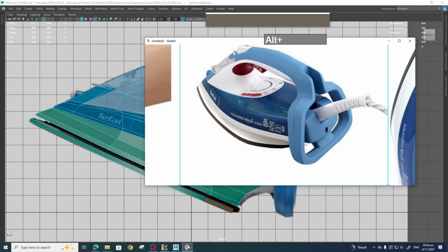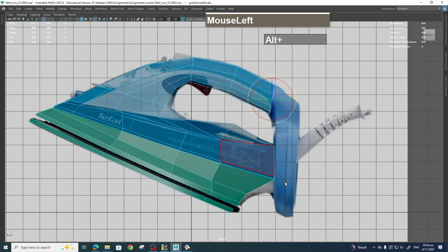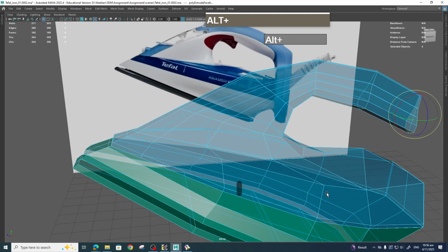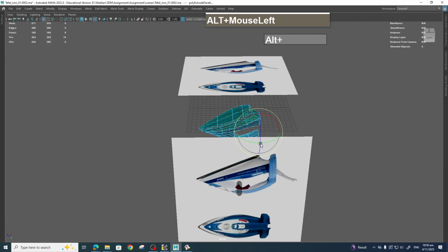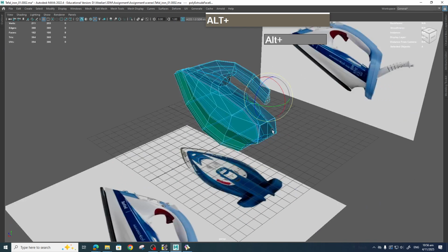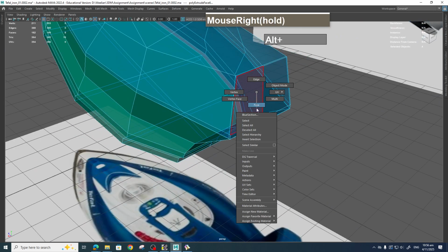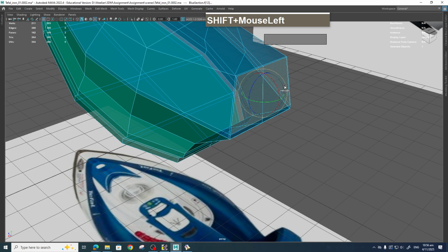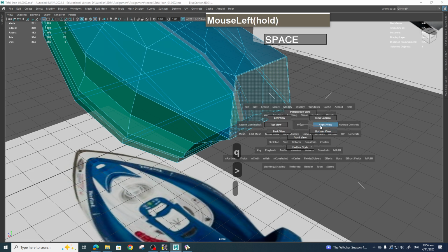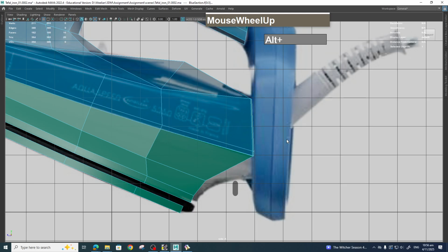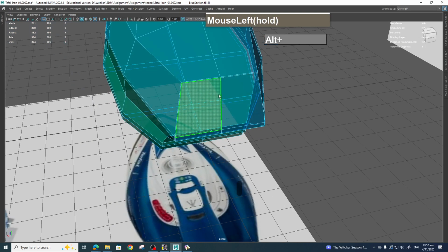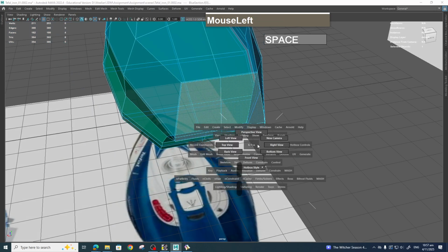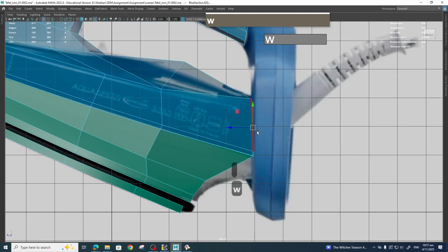And I just realized that the tail actually sticks out behind this area. So what that means is that this section, the tail section of the iron, is extruded further. So I'm going to select these faces, press Shift full stop to increase selection. Let's go to the right view. And actually on second thought, I'll just need to select these four faces. Then go to the right view and extrude all the way to here.